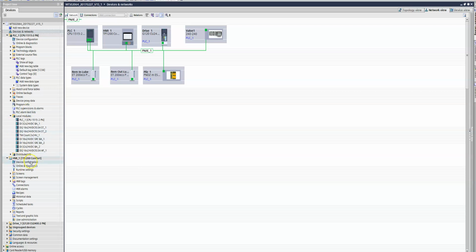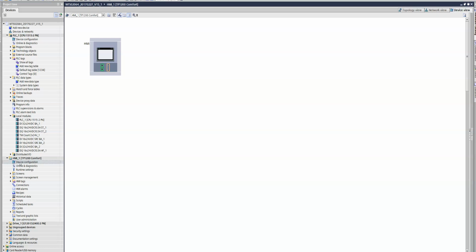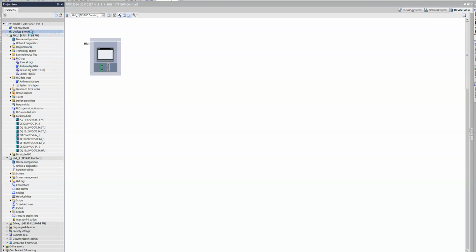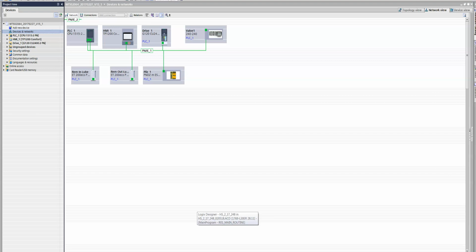One of the other really neat features is the highly integrated HMI. I can integrate it into my network, but then I actually also integrate it directly into my PLC program. Whereas with FactoryTalk, it can network to your 5000, but it will not be fully integrated.